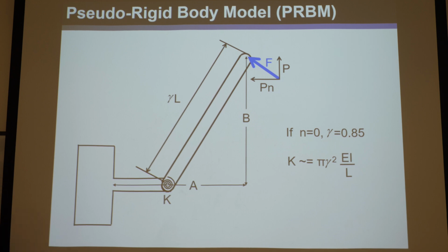But the idea, again, is you take some complex, nonlinear, very intense compliant system, and you can simplify it to come up with a rigid body analog that moves similarly, for government work, right, first order approximations that get you in the ballpark and kind of match the stiffness, and then you're able to analyze it much more simply, right?